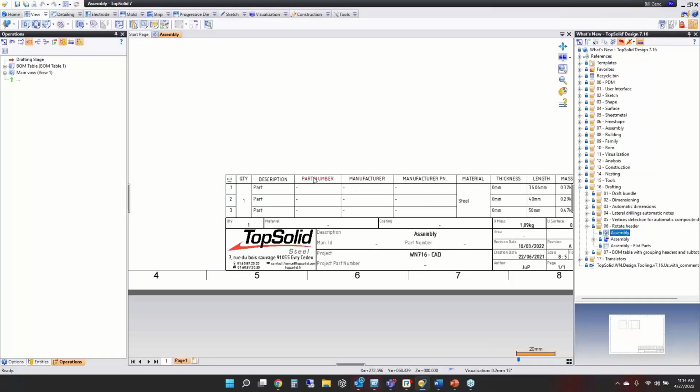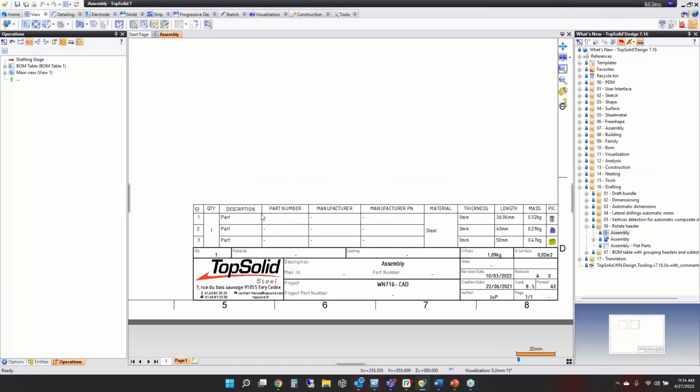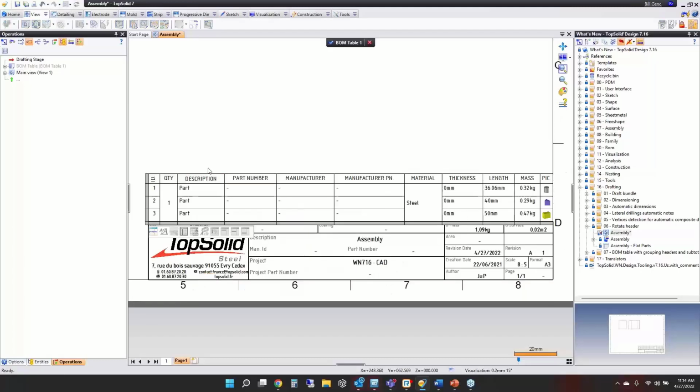All right, so we have this bill of material here. I'm going to take this bill of material and I want to edit the table. From there, right now, these have always been non-modifiable, you couldn't do anything with them. So first, you can now make them modifiable. I could change the text if I want to items, who knows.